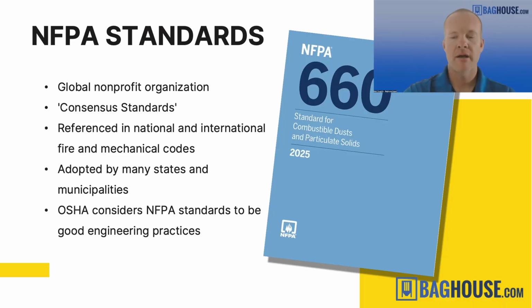You also need to have an NFPA rated airlock or drum kit or something like that at your dust discharge to make sure that the explosion is isolated there as well.